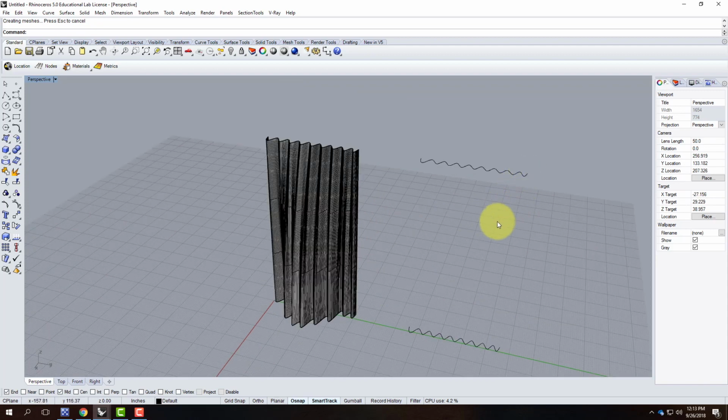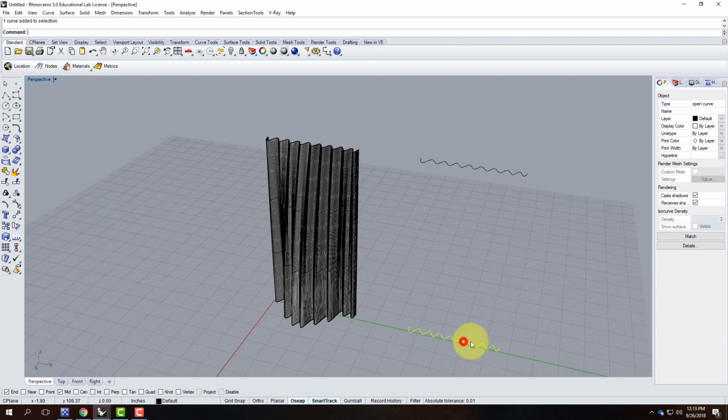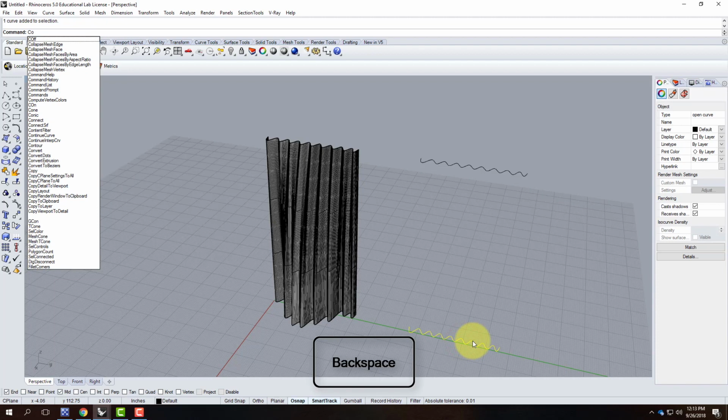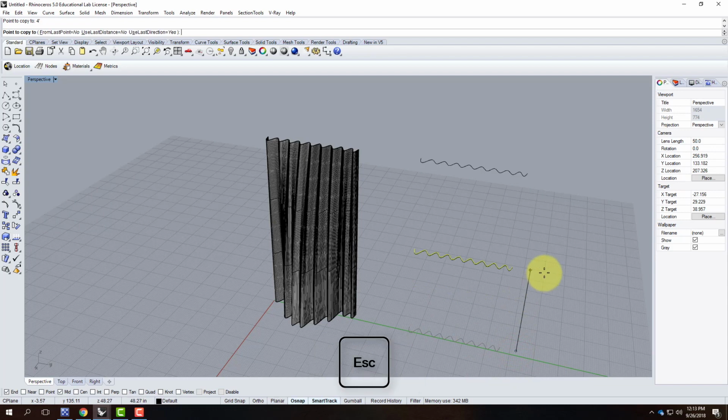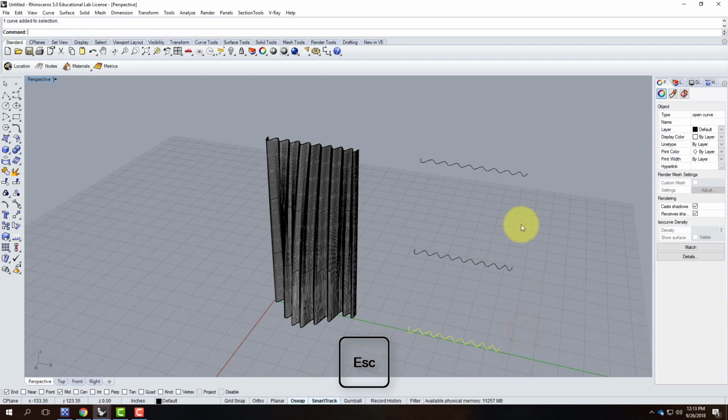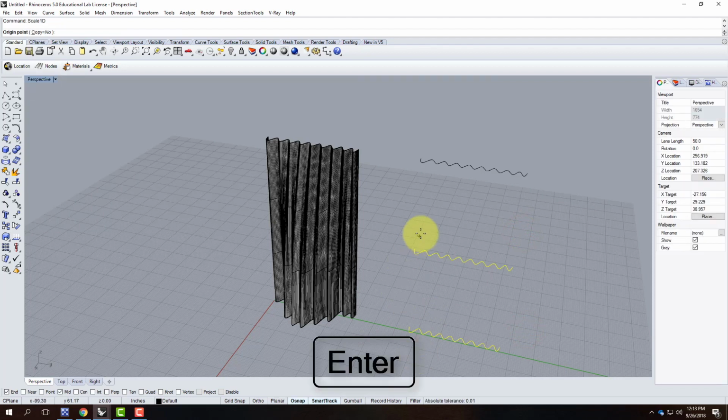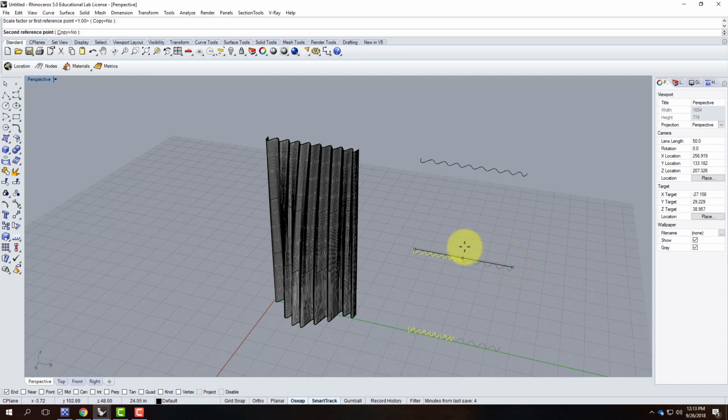If I wanted them to swag to one side, I could take the same thing here. I'm going to do one in the middle here. There we go. And I could do a scale 1D on these. So let's take these 2, scale 1D. And I could say, instead of being that long, I want them to be a little bit shorter.